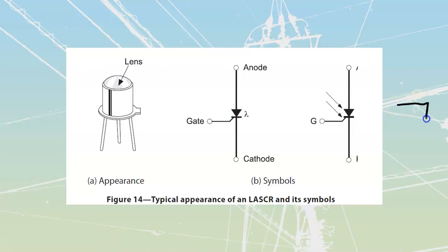We can take an N type of material, and a P type of material. They're going to be really, really thin. N type of material has an excess of electrons. P type of material has an excess of holes. In between those two, we've just got ourselves a depletion region. Okay, it's a standard diode when we take a look at one of these.